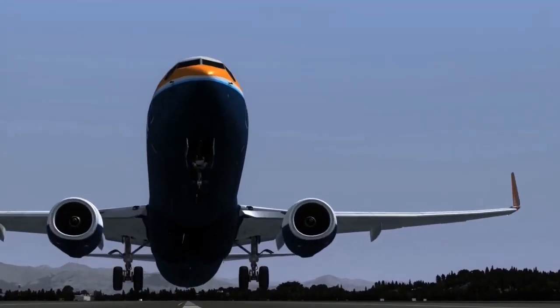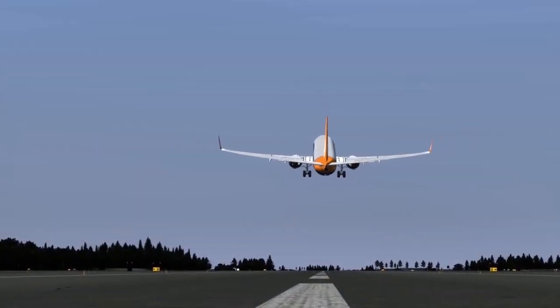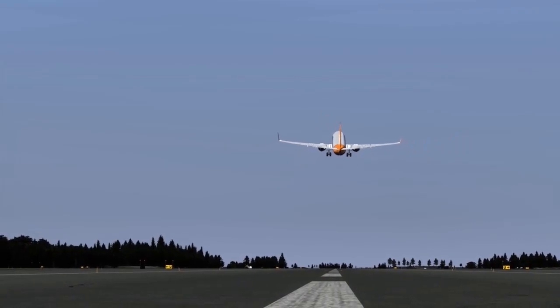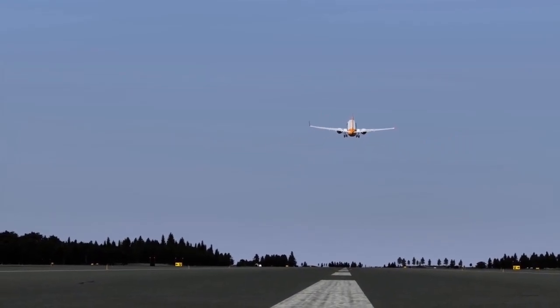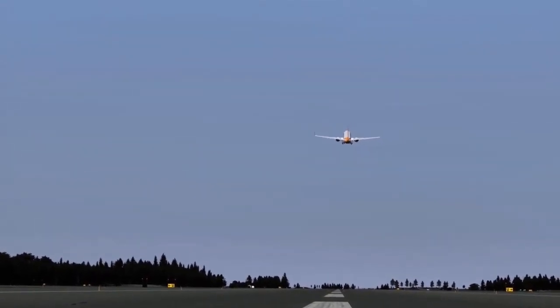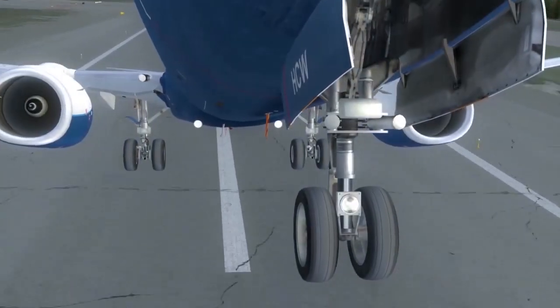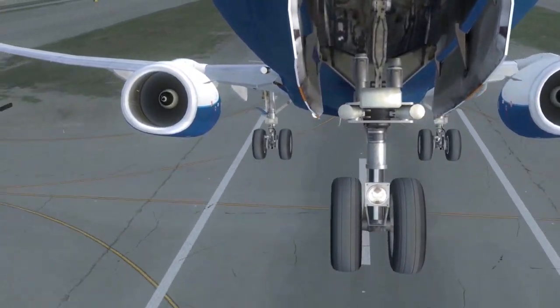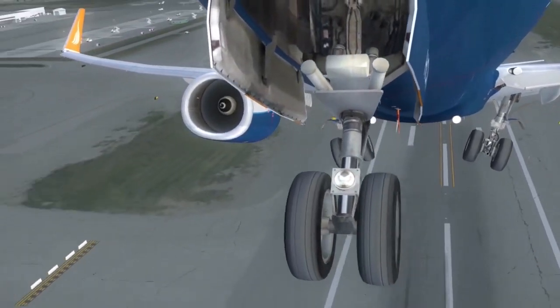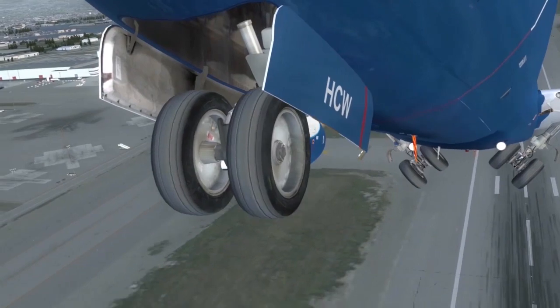To start the takeoff phase, the pressurization system must recognize the following conditions. N1 on both engines must increase past 60% for 1.5 seconds or more. N2 on both engines must increase past 89% for 1.5 seconds or more.